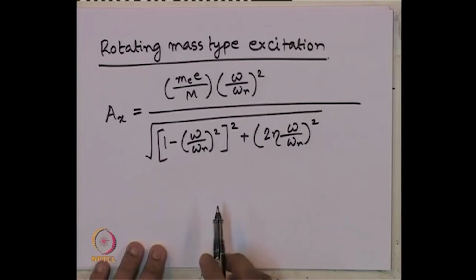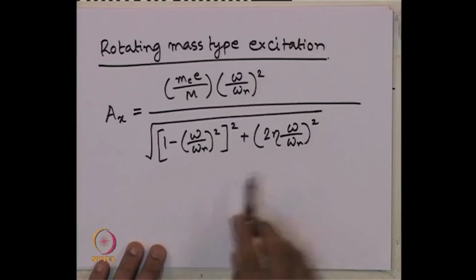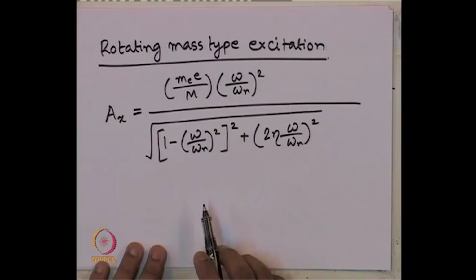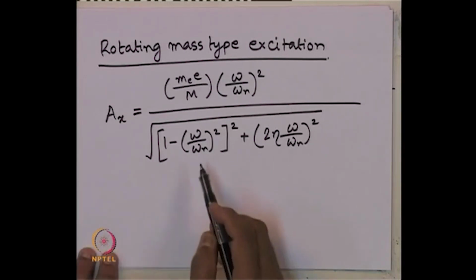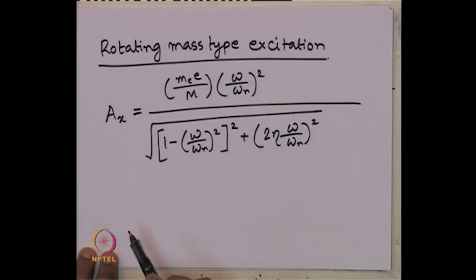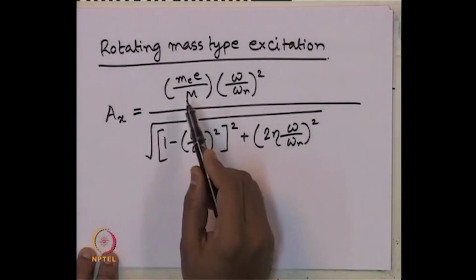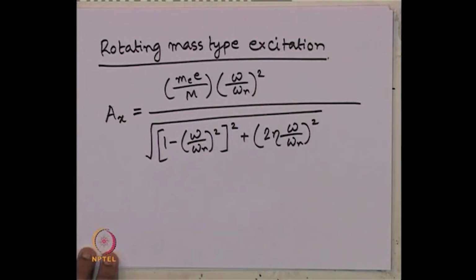This is again from our module 2 vibration theory, where we get this expression. Basically, it remains the same as for the vertical mode of vibration, the only changes being wherever the natural frequency etcetera has changed. And this mass imbalance is creating the horizontal type of vibration, which is another important point to be noted. Though we have kept the amplitude of load the same in the problem, for vertical mode of vibration it is acting vertically, whereas for horizontal or sliding mode of vibration it is acting horizontally. So, that is the only change.